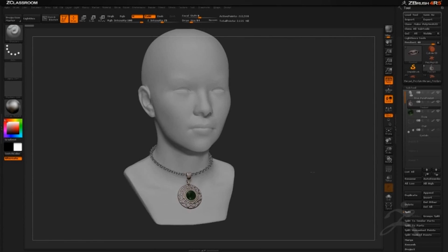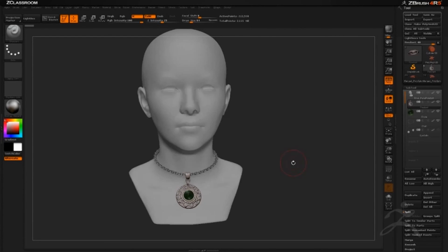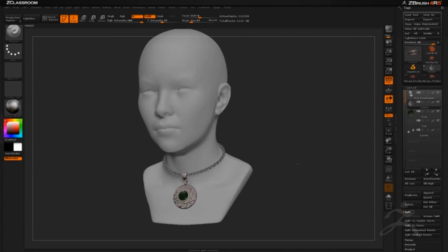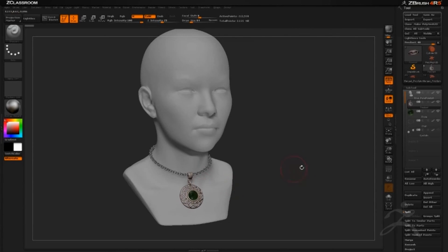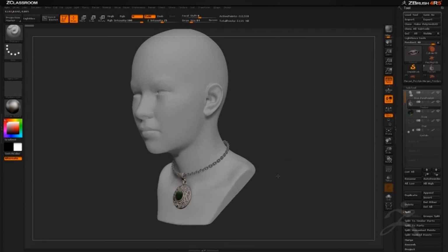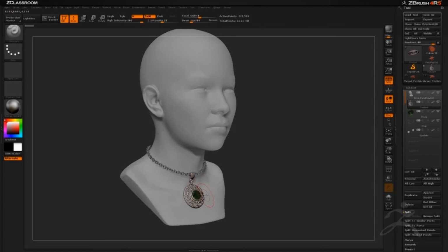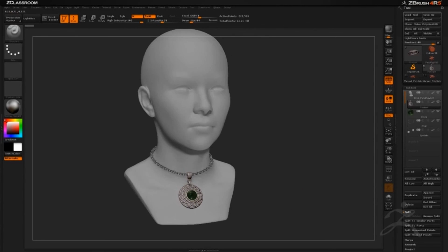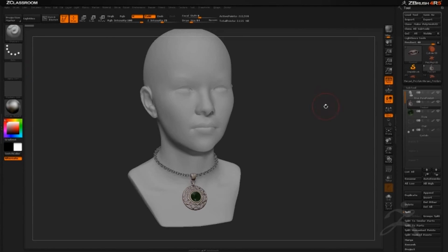So these panel loops in ZBrush 4R5 are extremely powerful, so don't just think of them as only being used for armor plating on models. They can be used for a wide range of things. One great venue for them is using them to generate jewelry assets. They work really well for any of the openwork stuff you would like to create on any model. You just literally make your outer structure and then apply your panel loops, and you get this nice feel to objects inside of ZBrush.